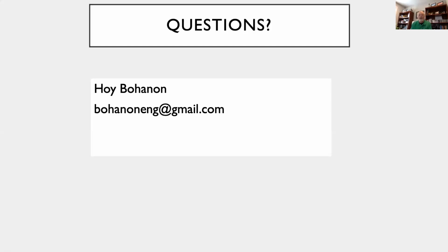Because that made it all go away in the charts and the handbooks. But the idea that we've got a 40 to 60% for us, and it's percent, it's not dew point, is more healthy is correct. So to the extent you can control your environment, like your home or someplace else, keeping it between 40 to 60% will keep everybody healthier. But it's not in the minimum standards because the committee was not convinced that's an appropriate minimum, but it might be a best practice.